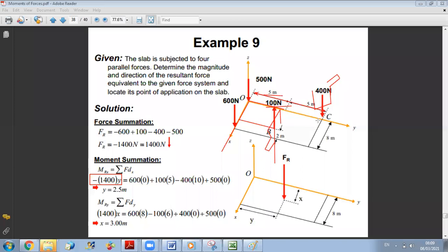Because it's a negative moment, then when you displace your resulting force, it should also have a negative moment. Okay? So what you were able to do now, you were able to reduce here at 1 force, Fr, and you got a negative moment along x. Okay, so now, because it's a negative moment, how you should displace your resultant force, if you want to produce the same effect, you should have your force displaced in a way to produce a negative moment.